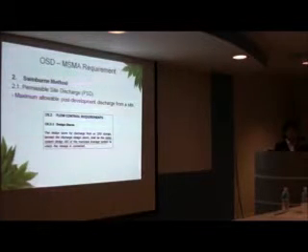In order to calculate the Q, we need the frequency of the storm, the ARI year. To get the ARI year, how do we know what ARI year to use? It's actually based on the receiving drain capacity. Let's say the OSD is discharged into one drain. We look into that drain, which is designed for how many years of ARI. This is how we determine the frequency of the rainstorm.